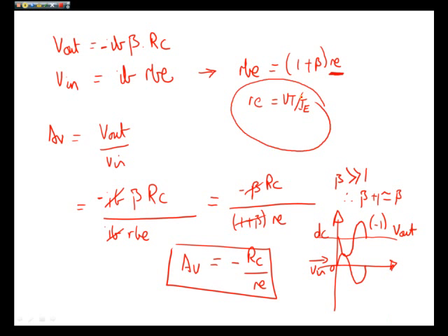Okay, how would you control this? You need to control the design by controlling RE. The only option you have here is IE, running the emitter current at different values. If you want to do anything more serious, you have to degenerate the emitter with a feedback component.